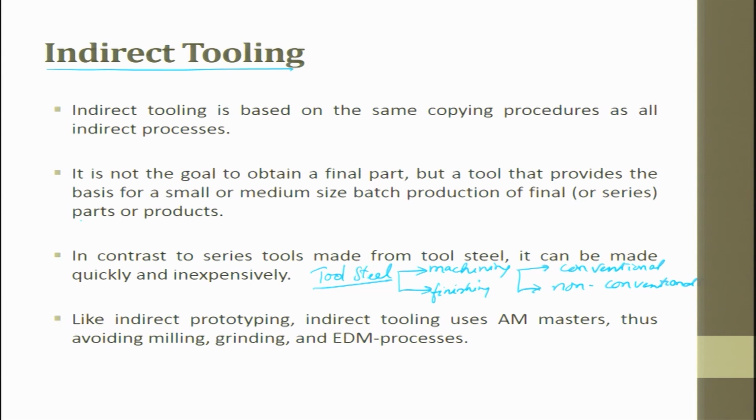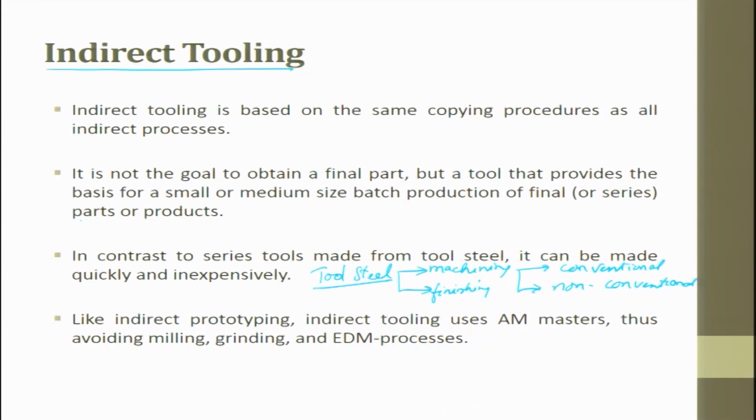There are several techniques which have come. In fact, people have started using metal filament wire for making parts. People have started using aluminum alloy powders and titanium alloy powders, wherein they directly make a die. And in fact, the finishing of late has also been improved. The biggest challenge even in rapid manufacturing or rapid prototyping is finishing.